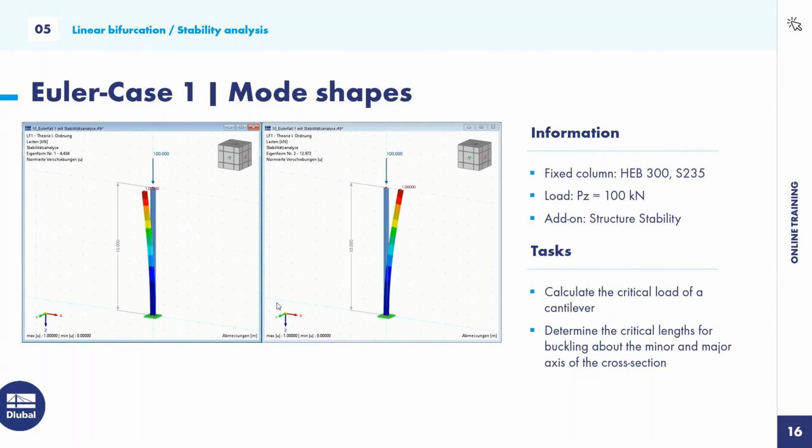And we want to compare Euler's analytical solution for this problem, which is generally accepted among the engineering scene, with the results of our numerical calculation. So the next task is, for this particular case, a clamped column under pure compressive load, to define the critical load factor of this cantilever column where it gets unstable.